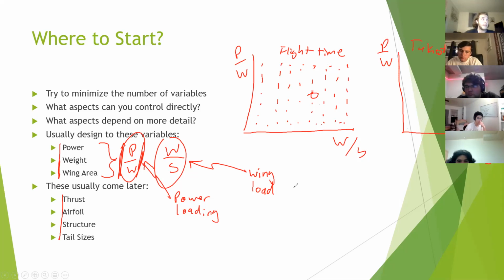If one of your assumptions is a CL max of, say, 1.1, which is fairly standard, but you want a high lift device for the takeoff distance, you can just plug that into this one. So you can have a CL max of, say, 1.5 with your high lift device, and do those calculations.